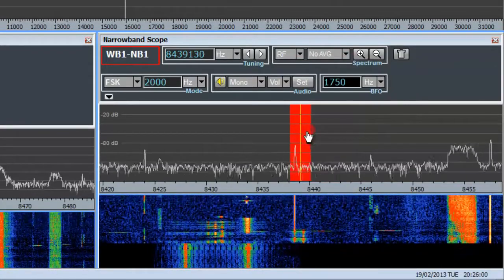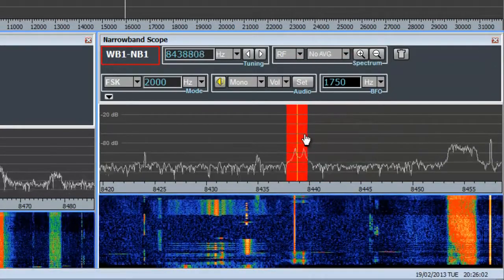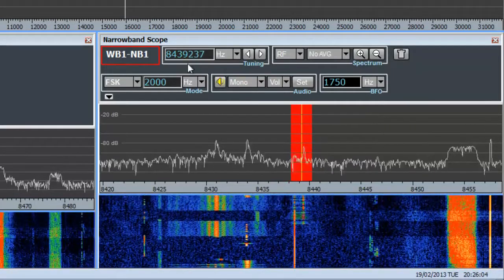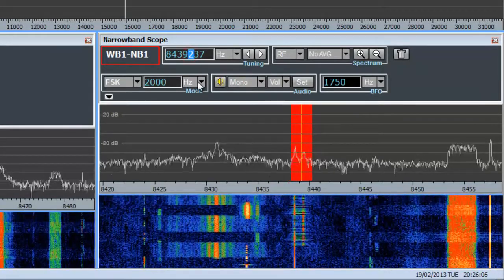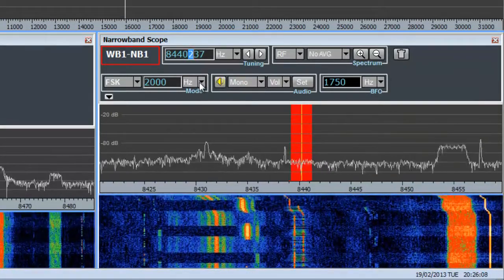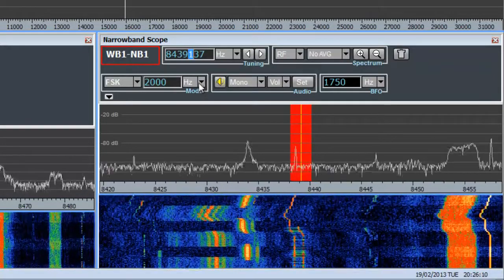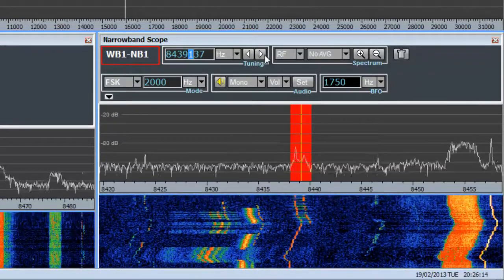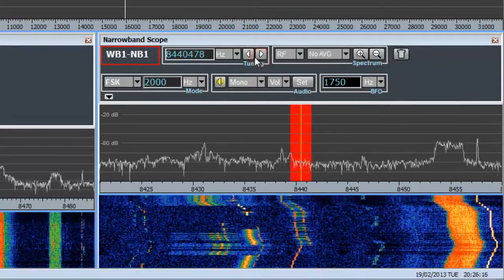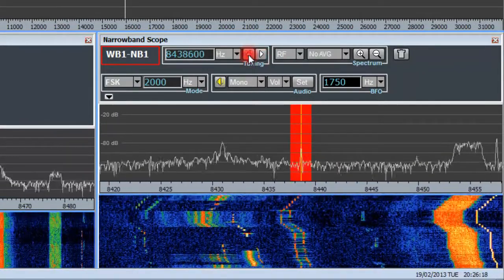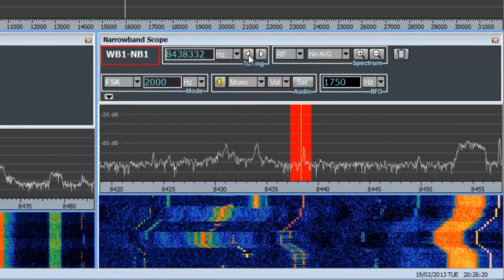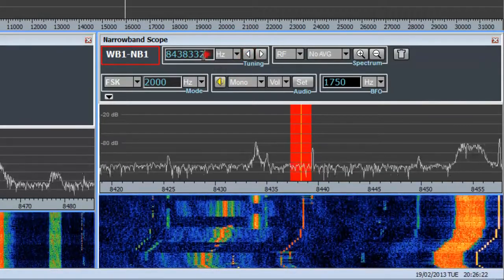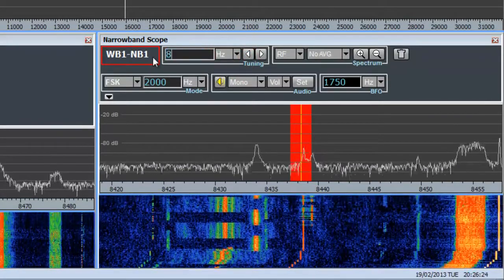Fine-tuning of the narrowband channel can be by dragging its shaded area, by turning of mouse wheel up or down after selection of a digit in the frequency edit box, by clicking the frequency shift buttons, or by editing the frequency directly.